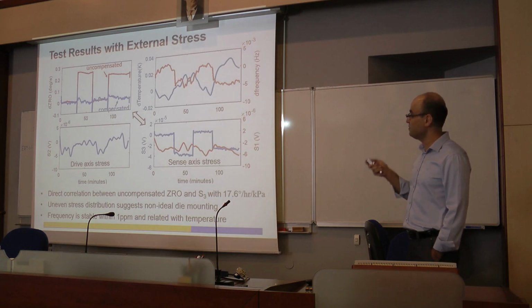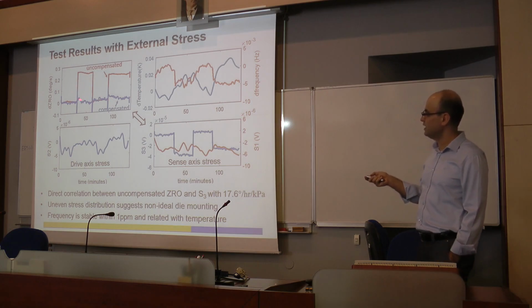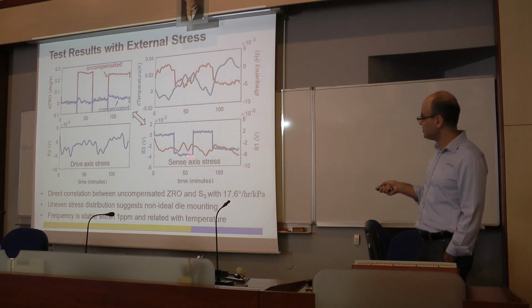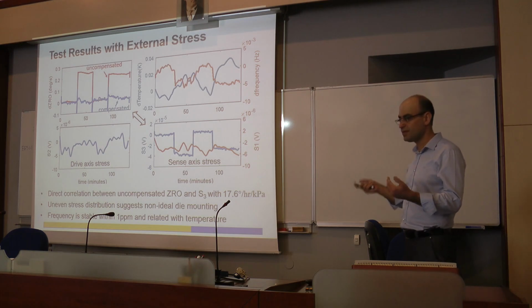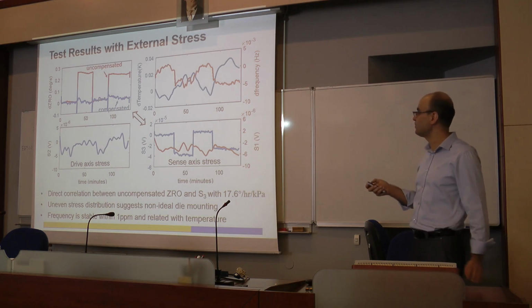And this is the result. This is the gyro output. The red one is the uncompensated output, with the copper weight left, right, right, left. And if I look at the stress here, I'm measuring 3 stresses and one temperature: x, y, 2 x's versus 1 y.